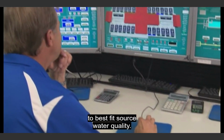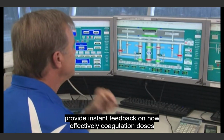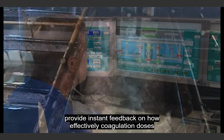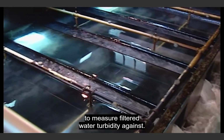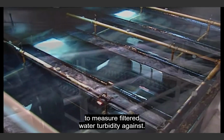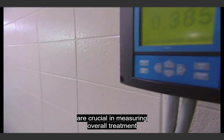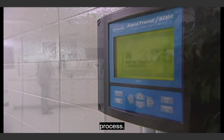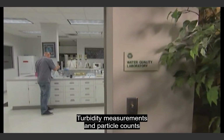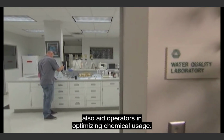Readings taken following clarification provide instant feedback on how effectively coagulation doses are working and serve as a benchmark to measure filtered water turbidity against. And post-filtration turbidity and particle counting are crucial in measuring overall treatment performance and the effectiveness of the filtration process. Turbidity measurements and particle counts also aid operators in optimizing chemical usage.